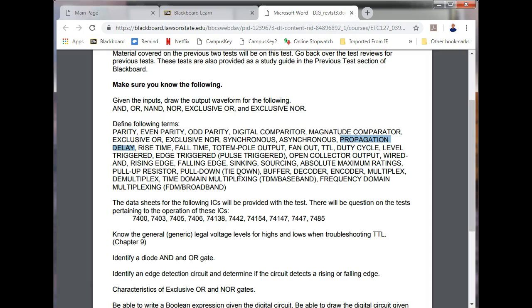Then we have pull-up resistor. Is everybody okay there? Pull-down resistor. Do I have that on there? A buffer. Everybody okay there? What's a buffer? Just pass through. You get a propagation delay. We do buffers. I think the example we use is to increase fan out. You can bring the output of a gate to a buffer, and then it'll give you the fan out of the buffer, right? You understand that? We use it for isolation, so they're used. We normally don't teach them because they're not a gate. They're not one of the 5 basic gates. The 5 basic gates do something,